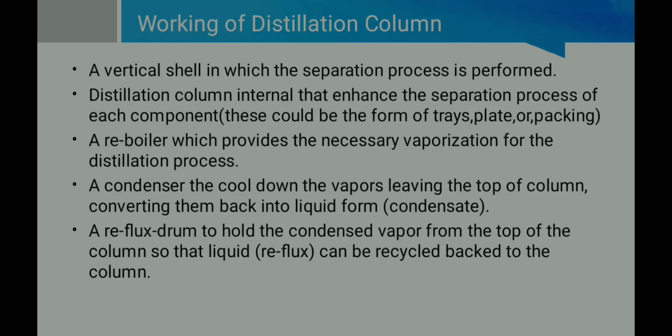Now let us see the working of a distillation column. A vertical shell in which the separation process is performed. Distillation column internals that enhance the separation of each component. This could be in the form of trays, plates, or a packing. A reboiler, which provides the necessary evaporation for the distillation process.